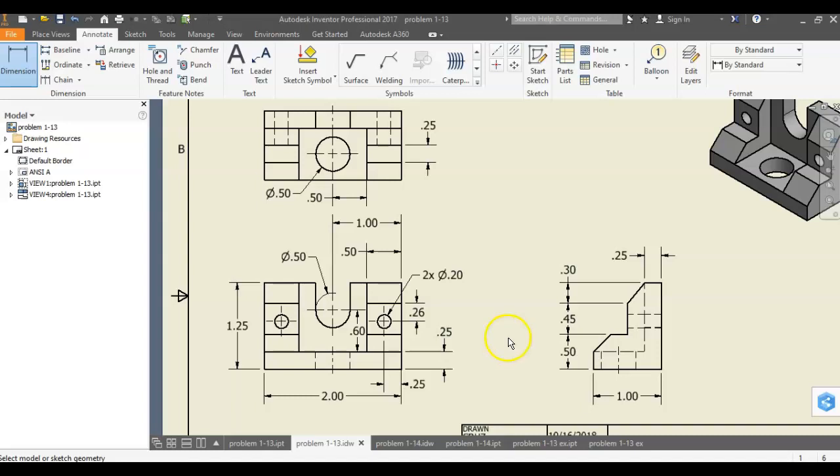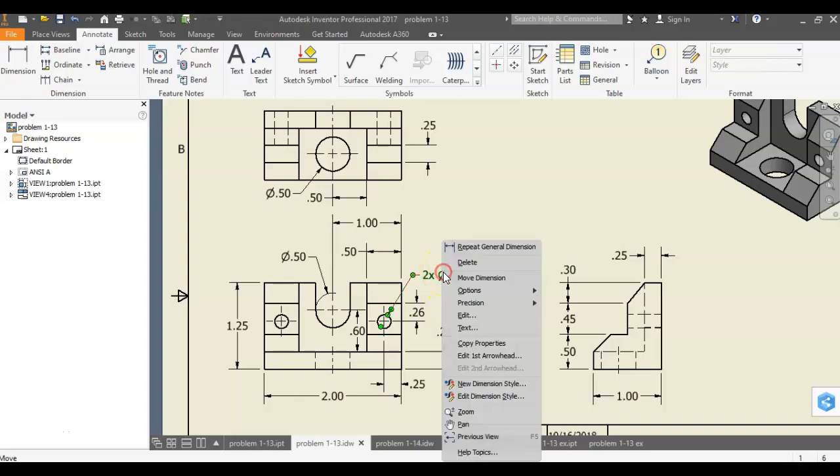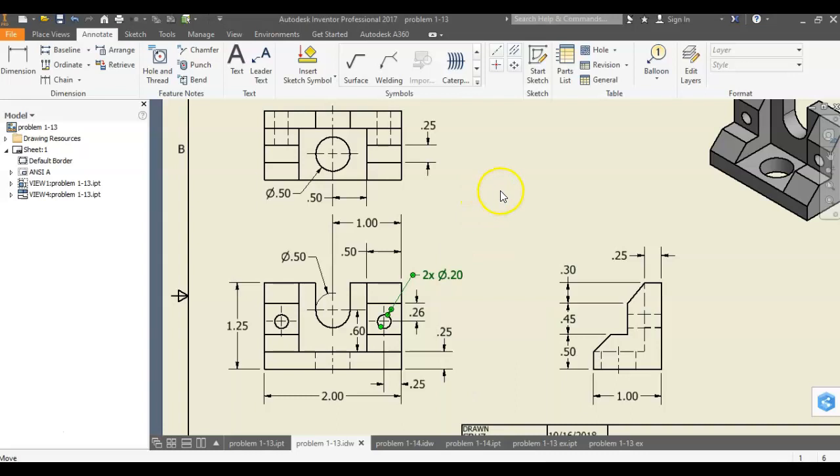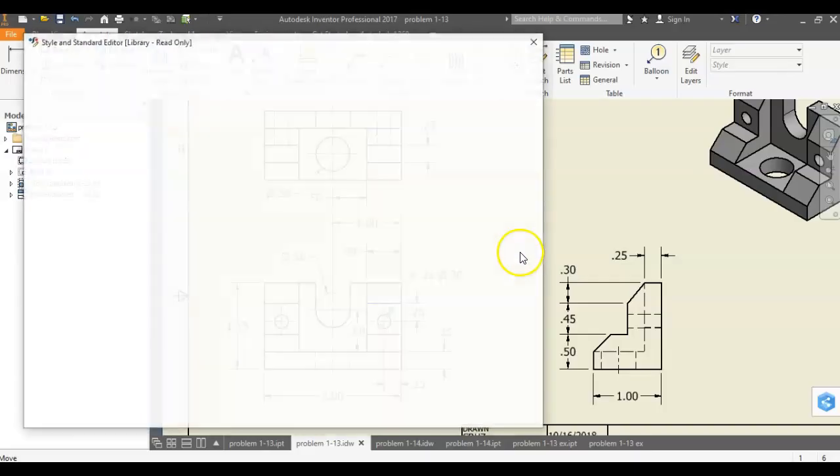And also, you're going to want to change your fonts to Technic. So right click on your dimension text. Well, tap escape before because it was still selected. And then edit dimension style. My menu's going to pop up here in just a second. Okay, I'm still here. Don't worry, it's just being slow.